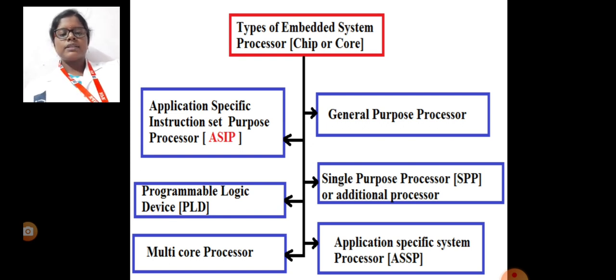A timer may dissipate a constant power even in a wait state. Hence, these three circuits are powered separately. From the supply, there should be separate interconnections for pairs of VDD and VSS pins, analog ground and analog reference, and analog input voltage lines.